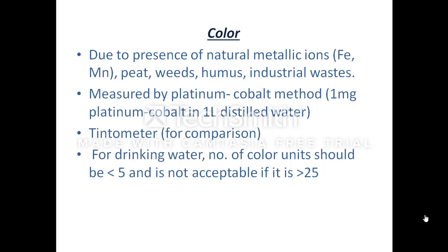However, this method can't be used in field. So for field we use other method where the properly calibrated glass color discs are used instead of standard colored water for comparison. Now for drinking water, the number of color units should be less than 5. However, it can be tolerated, but greater than 25 is not acceptable.